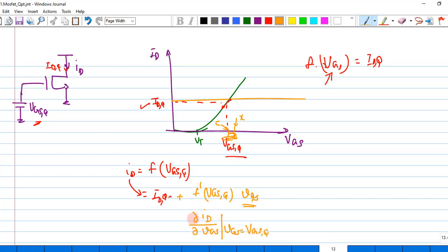So rather than writing a derivative like this, I can write this derivative as this divided by this quantity. It is exactly the same thing, okay? I have replaced this composite signal of my VGS with the known value of VGS, which is the DC value, okay? It has been evaluated around that particular spot. So in general, the composite signal could be written as this quantity, which is the IDQ, plus, sorry, I have mixed the term.